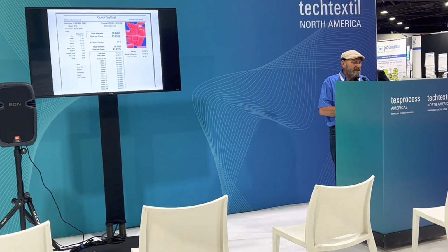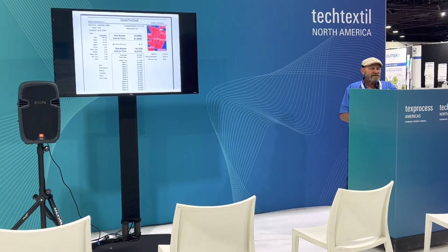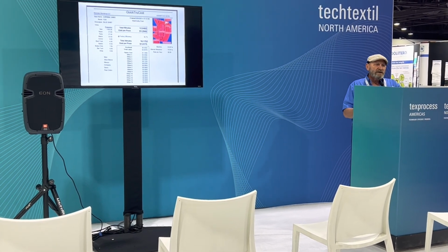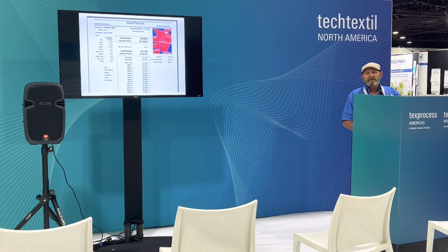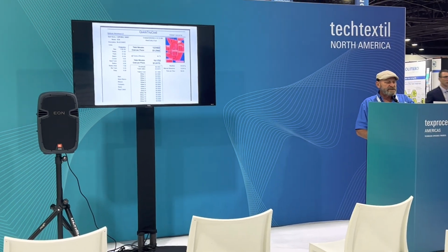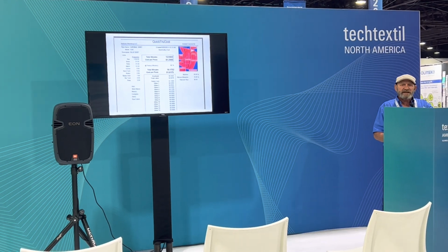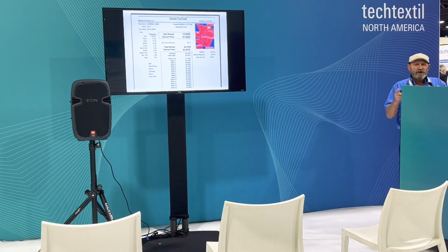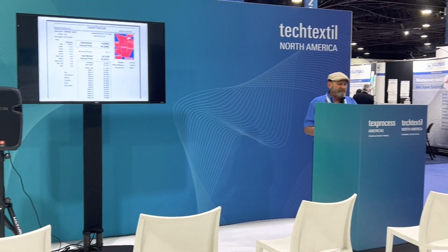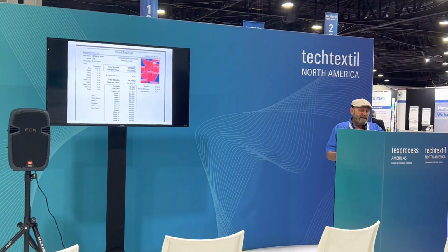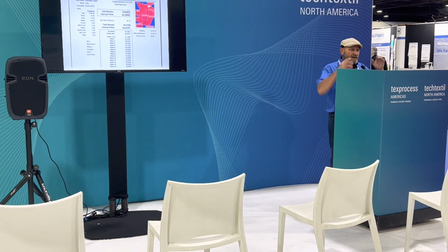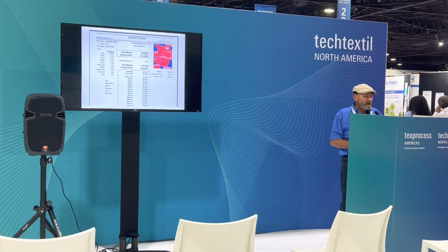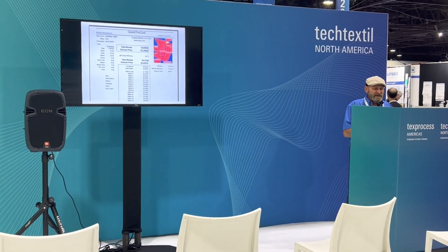Once you enter that information, it will come up and tell you the total minutes you can see on the screen. So your total minutes is like 12.94, and the labor cost based on whatever your hourly rate or your base rates are, it'll give you that cost. And the next numbers you see down below, if you put in an efficiency of the plant, so you know your plant does not run at 100%, no plant does, and you know what your plant efficiency is, you plug that in, so that will add in your inefficiencies, just bringing the time value up and the cost. So that's just a way of taking what was 100% cost and basing it on exactly what your plant history of productivity is.